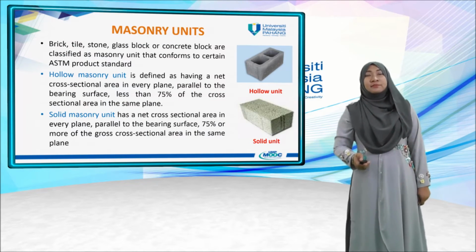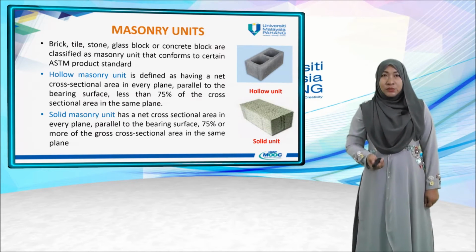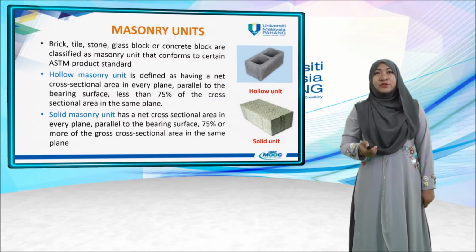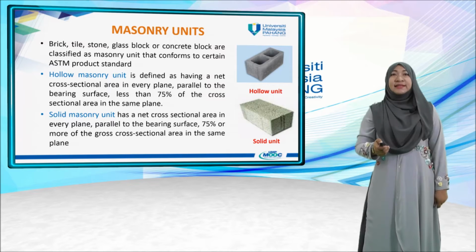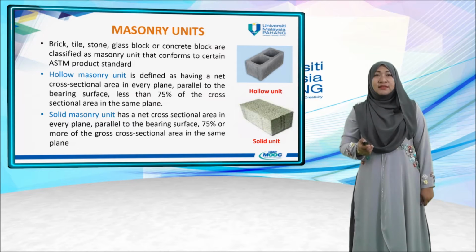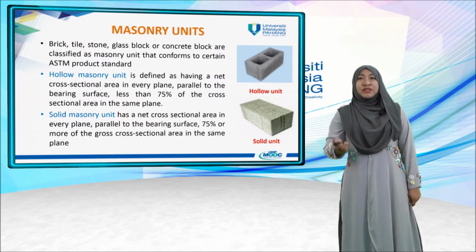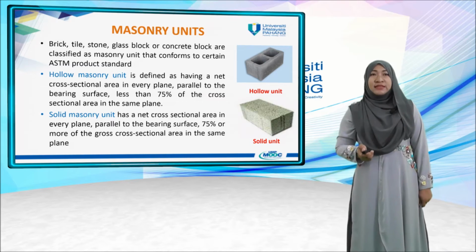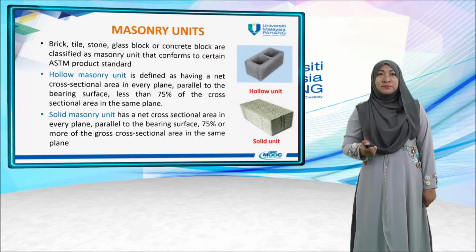There are other masonry units. Brick, tile, stone, glass block or concrete blocks are classified as masonry units that conform to certain ASTM product standards. A hollow masonry unit is defined as having a net cross-sectional area in every plane parallel to the bearing surface less than 75% of the cross-sectional area in the same plane, as shown in the figure. A solid masonry unit has a net cross-sectional area in every plane parallel to the bearing surface of 75% or more of the cross-sectional area in the same plane.